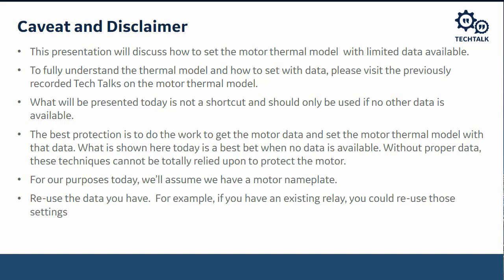It'll also have some settings around the curve. And it's not really settings if it's electromechanical, but it's the same thing as settings. You should reuse those as much as you can, because that device has been protecting that motor for some time, and you should reuse those.